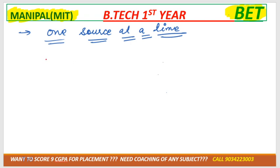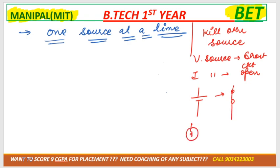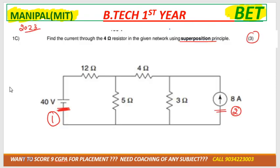Okay, so what we'll do with the other source, we need to kill other source. How can we kill other source? That means voltage source must be short circuit and current source must be open circuit, right? So voltage source is like this, that must be short circuit, and current source must be like this, that must be open circuit.